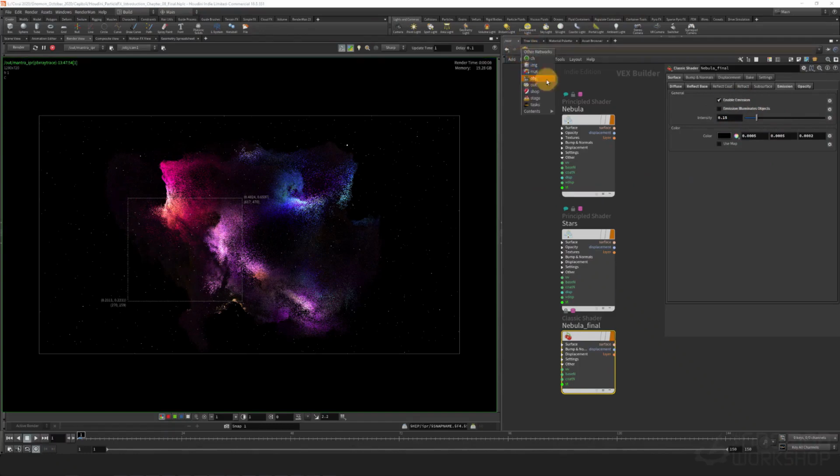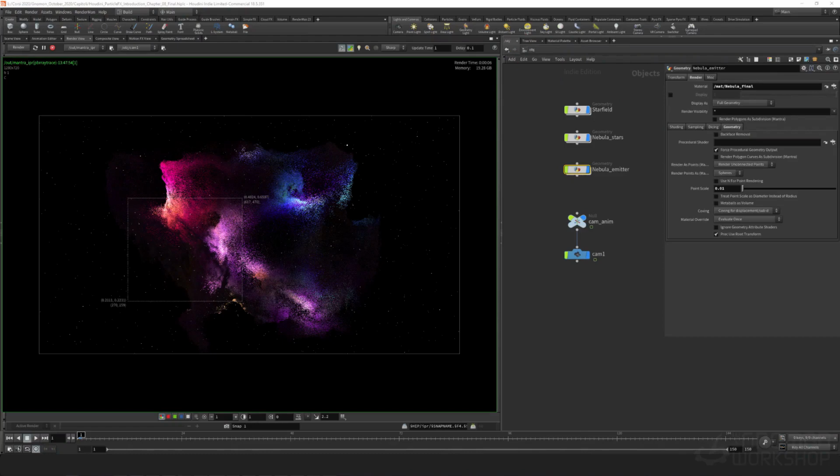Let's go to the particles because we have to take care also about the particle scaling. And we go to change from sphere to circles. With circles we are taking care about bidimensional stuff. So each grain, let's say each pixel, is not 3D, but it's just a point. And then we say that we like to have a bigger scale. Now it is going to have a really low scaling. We go for 0.015, so it will be a little bit bigger than before.